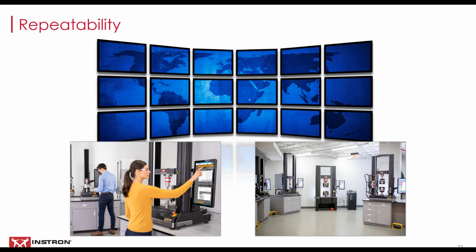When there's differences in that data, it's necessary to understand the root cause. This can really be a challenge as there's so many factors that can affect test results. It might be due to the lab environment, because heat and humidity affect load readings. Maybe the test systems are from different manufacturers or different vintages. It could be that the test methods or load strings being used are different. It might even come down to different operators having different levels of training and experience. Getting to the root cause of those differences can be really a challenge.